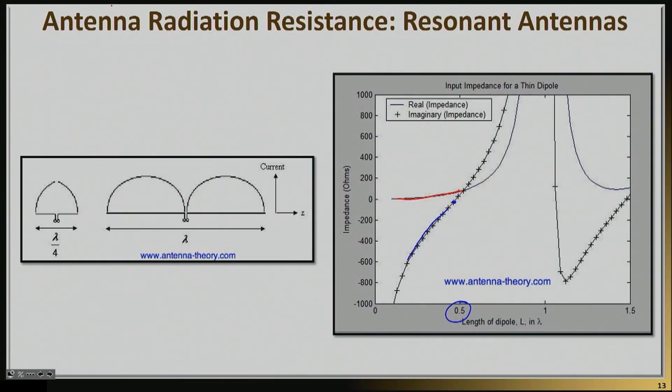And that will be essentially the radiation resistance that you have to match with a matching network when you design this antenna. Now, what is also interesting to notice about a resonant antenna like the dipole is that away from resonance, the reactance of the antenna actually changes dramatically. That's a direct consequence, of course, of this being a resonant antenna, meaning it works well only at its design frequency. And away from it, it develops a very high value of reactance, which means it becomes very, very difficult to match those antennas.